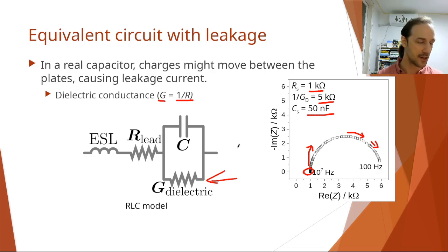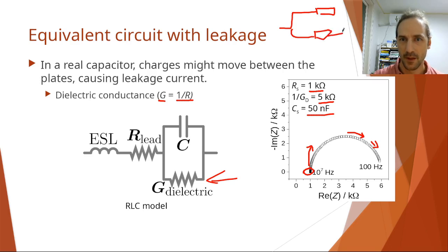How you should understand it is that, for example, if we have parallel resistors and one of them is much smaller than the other, let's say this is R1 and this is R2, and R2 is much smaller than R1. In that case, most of the current will move this way, right? Some of the current will go towards the higher resistance, but most of the current will flow through the lower resistance resistor.